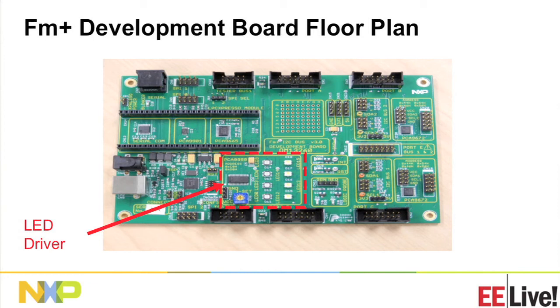I also mentioned we have a 16-channel LED driver. This is an NXP product. If you know about driving LEDs, you usually expect to see a resistor associated with the LED. This device is a constant current driver, does not need the external resistors, so the layout around here is quite clean. There's no parts on the back of the board. The device directly drives the LEDs. We have 4 white LEDs, and we have 4 clusters of RGB, 16 channels total.